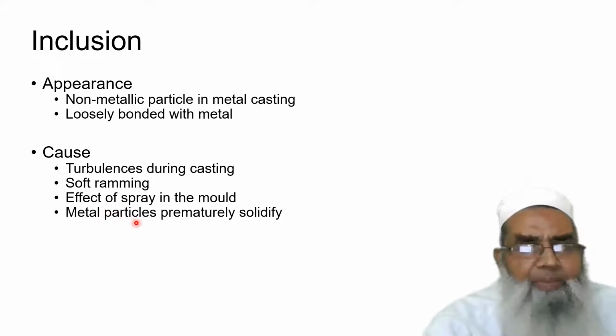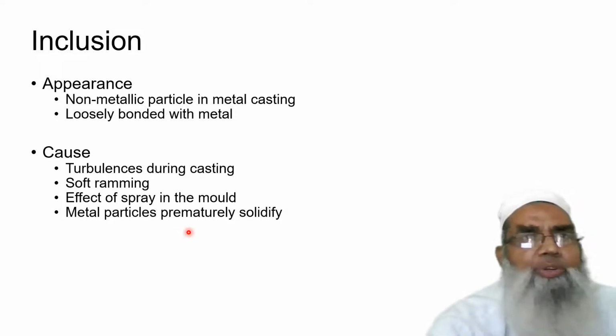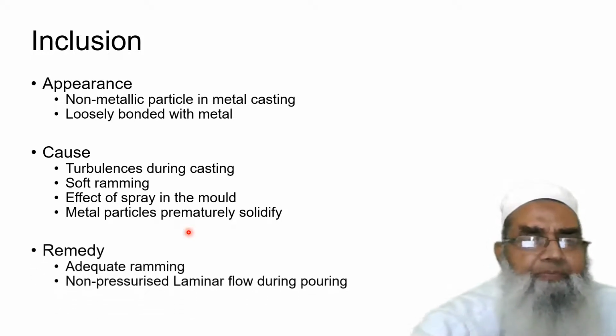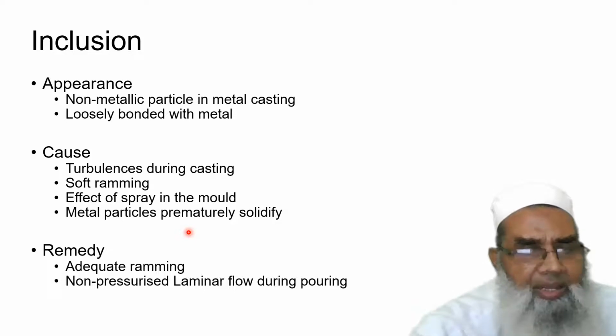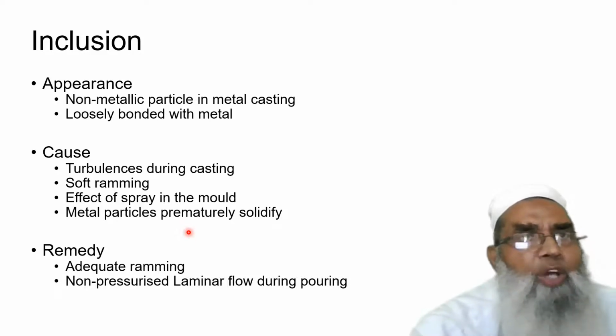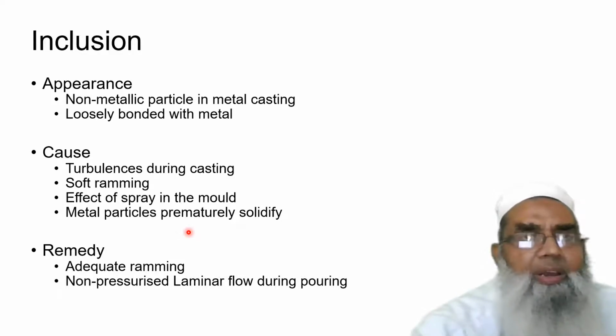Basically it happens that when the metal particles solidify prematurely, this may cause a particular type of inclusion. Therefore adequate ramming and non-pressurized laminar flow will of course avoid the inclusion of foreign particles in the casting.